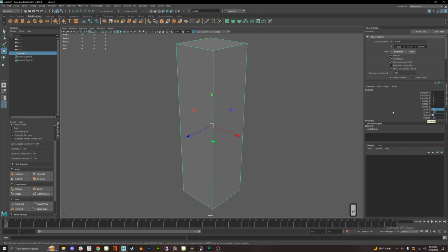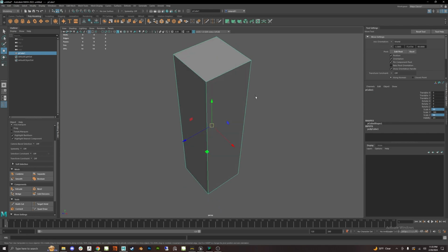I'm going to use Control to select both of those, make them highlighted, and set this to 50 centimeters. The reason I did that is because the typical human, the scale mannequin character in Unreal, is 180 centimeters tall, or 1.8 meters. When I look at this object in the scale of our scene, we're dealing with 180, 50, and 50. Those are kind of hard to deal with, especially when we start dealing with larger scenes.